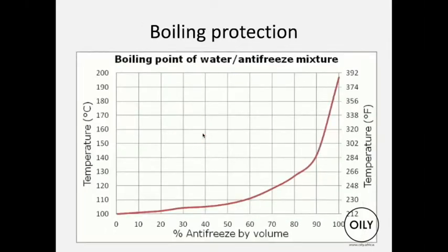And then boiling protection, you can see water boils at 100. At 60%, it will raise the boiling point by 10 degrees. At 90% it raises it by about 40 degrees. So it does raise the boiling point of the water in the cooling system.